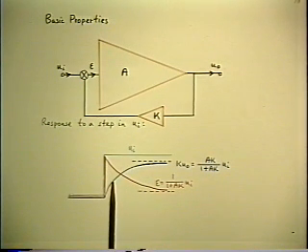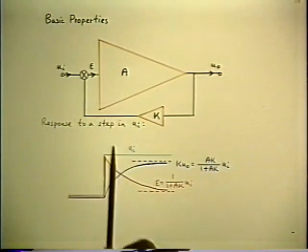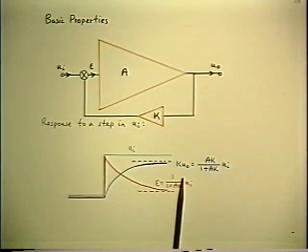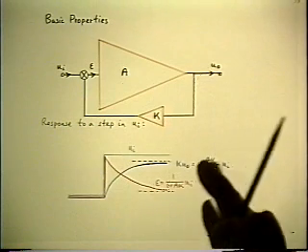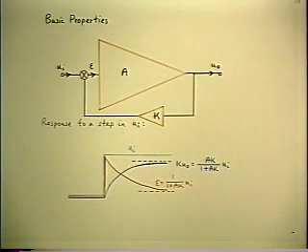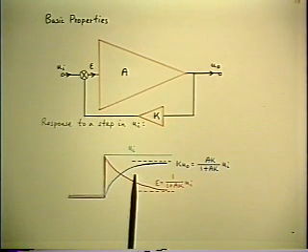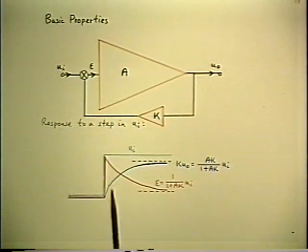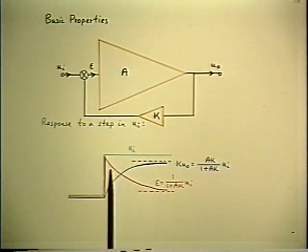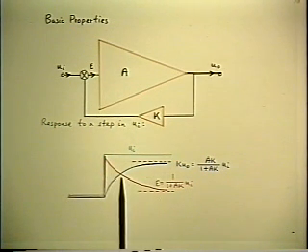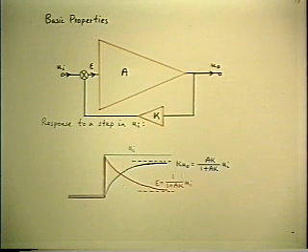What happens, of course, is the problem will divide down into a sequence of linear problems as one stage after another comes out of saturation or cutoff and recovers from the overload. The net result is the transient won't be a single exponential. It'll be a sequence of totally different solutions, probably mostly linear, because of current sources feeding into capacitors.